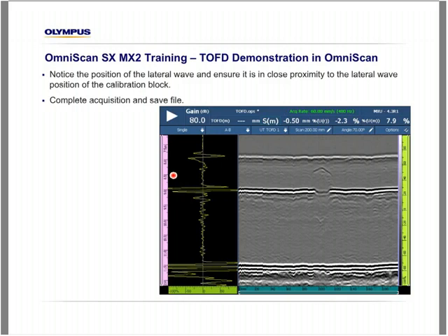It was uncalibrated. The calibration was removed for the actual inspection, but my PCS value, the probe center separation value, the physical distance of the probes in the scanner, and the wedge delay was known and entered into the software. I only acquired the data at an uncalibrated state with a time scale only. This is intentional for reasons I'll explain shortly in analysis mode.